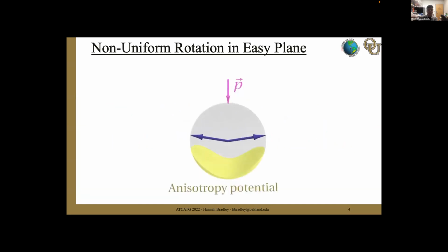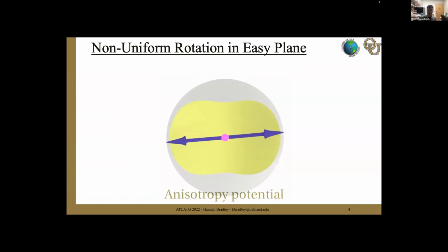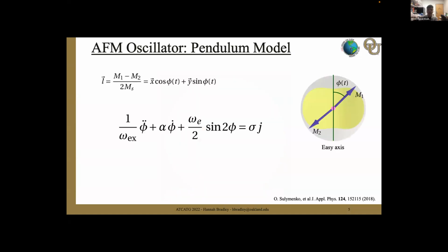The spin current acts on both magnetic sublattices and causes them to rotate. But the biaxial anisotropy of the AFM causes this rotation to not be uniform. The rotating spins create a spin pumping signal, the magnitude of which is proportional to the rotational speed. And the non-uniform rotation at this terahertz frequency results in a sequence of very intense, very short spin pumping spikes.